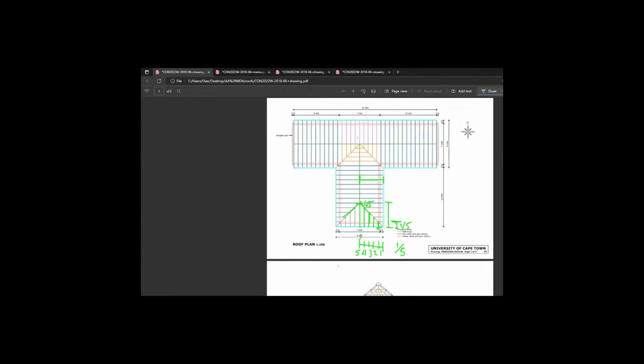So what that's saying is, as we travel across this green line up the slope of the roof, this piece is 1/5 of that one. This piece here is 2/5 of this longer red line, right? This one is 3/5 of the longer one. And here we have 4/5. And the last one, obviously, because you can see clearly that we've now reached the full length. So 5/5 is not actually applicable. Once you get to 5/5, you should be aware that you've now reached the full length and it is no longer considered jack rafter, right? So you should never reach 5/5. This is your maximum, 4/5. It makes sense. It's fairly logical.